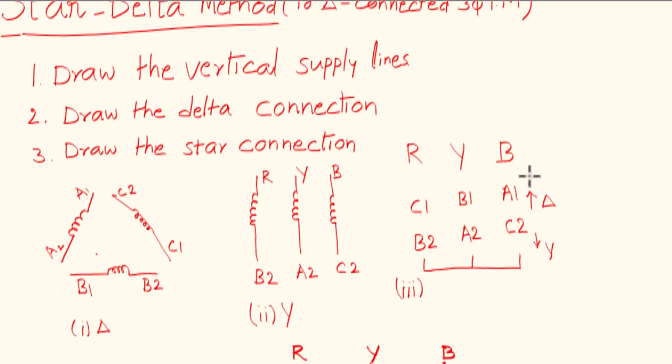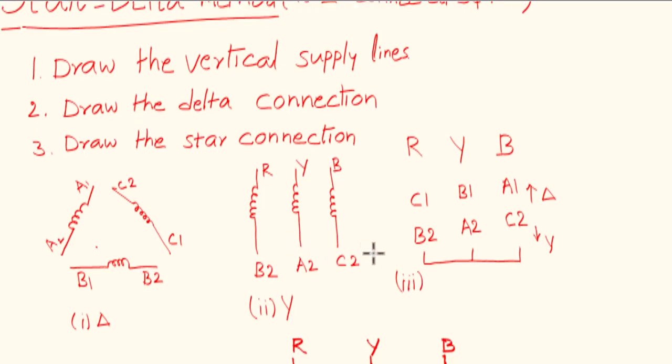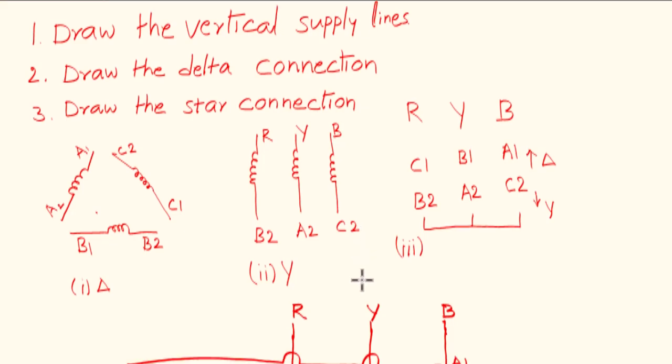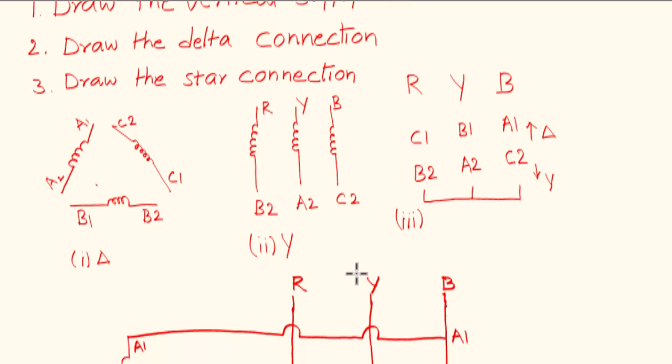In this method, there are two things to be found. First, what is the starting current when the stator winding is connected in star form, and then calculating that starting current in terms of the rotor short circuited current when the applied voltage is the rated value.